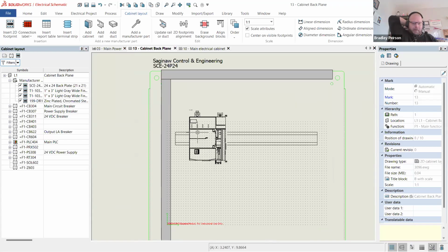Also on terminal blocks, which I'm about to talk about in depth. As I said, I was going to end this video like 20 minutes ago. As we do terminal blocks, I try to maintain at least 1.5 inches. We need some room for the wires to bend, and honestly, to get my fat digits in there to wire them in the first place. They usually don't have a required clearance because they're not generating heat. I try to shoot for 1.5 inches. That seems to work out for a nice, good distance where I can actually get in and do some work.